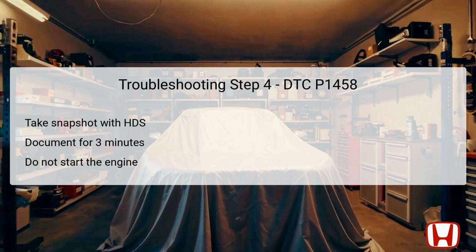Step 4 requires you to take a snapshot with the HDS tool for a duration of 3 minutes without starting the engine. This snapshot is crucial for capturing real-time data regarding the FTP sensor under controlled conditions, without the interference of engine operation. By doing so, you ensure that all variables affecting the sensor's performance are monitored accurately.